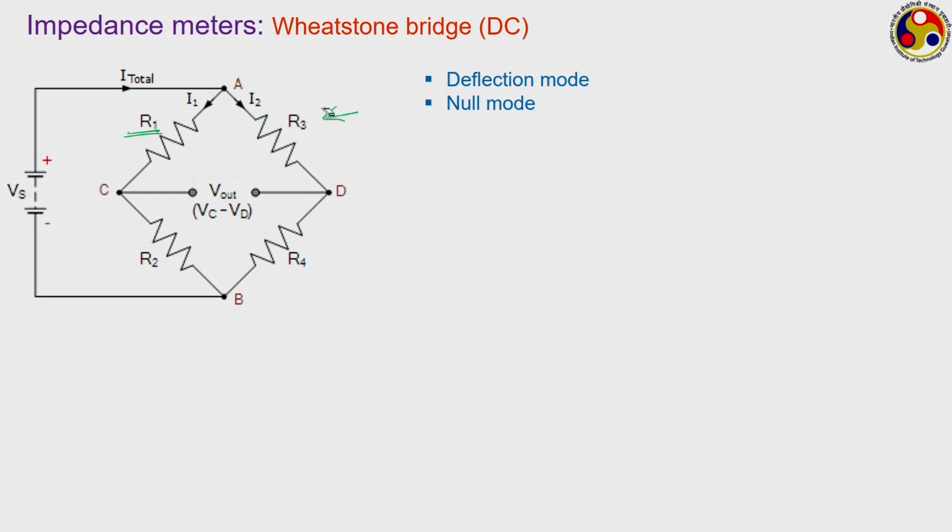Several measuring tools like strain gauges, which we are going to talk about next week, and several temperature sensing devices, etc., make use of Wheatstone bridges and get the actual output signal converted to a certain kind of electrical signal through this.